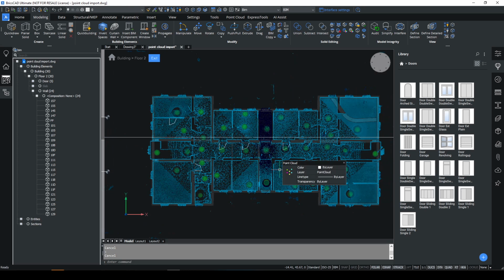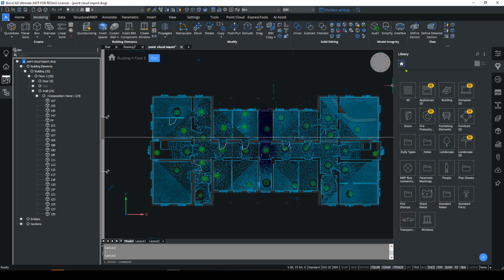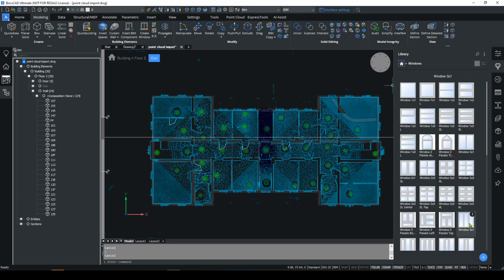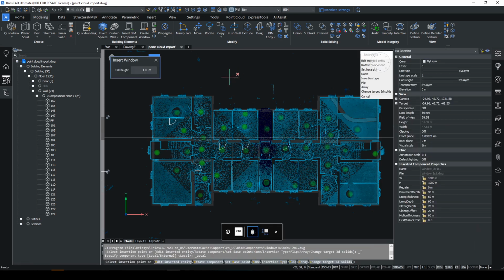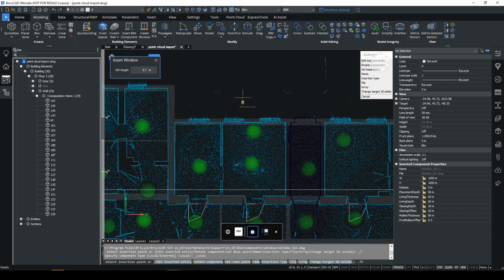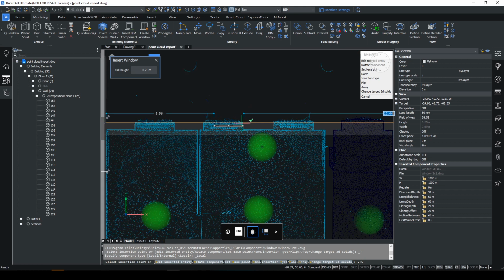The next thing that we would do is go and put some windows in. So for the windows, same process. We will go and click on the window option here, pick the window type, and it asks us for a sill height. Now, you would have measured this quite carefully for a serious job. I'm going to give it 0.75 for my height here. So let me just, 0.75 meters. And now, when I move into here, I can place a window.